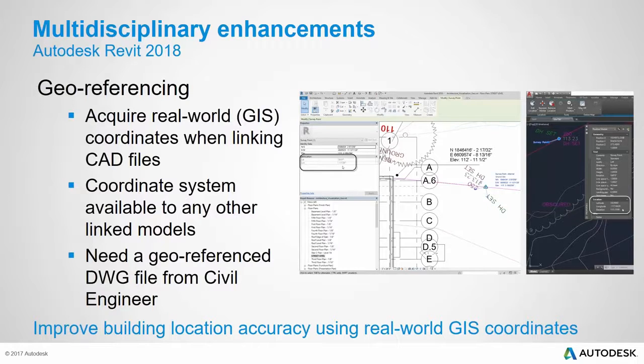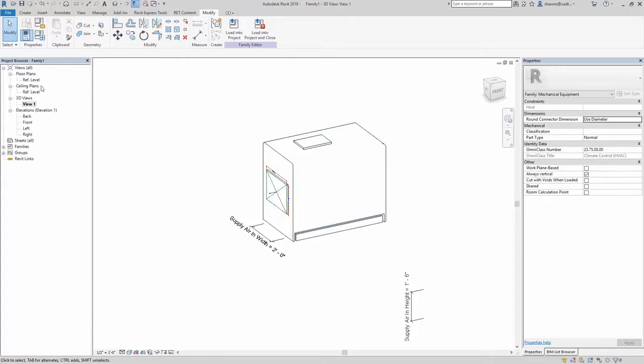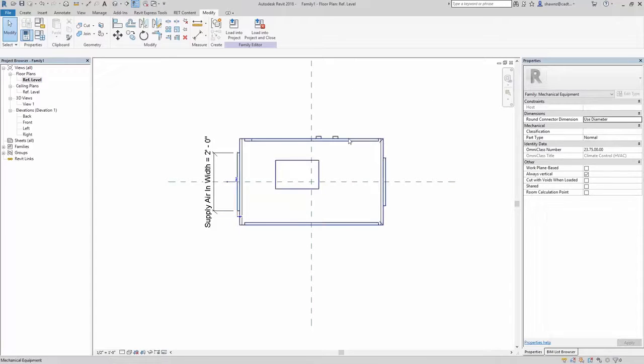And then the air handling unit that I just brought in here with that next little process here, the SAT, that's actually a 3D model, and it doesn't have a built-in 2D representation for this. So when I go to a floor plan representation, for example, this is showing me all of that solid geometry out there. If I did set this to like a hidden line graphic, I would see somewhat of a 2D graphic, but it's not automatically 2D. It is truly the 3D elements that are being regenerated in screen.